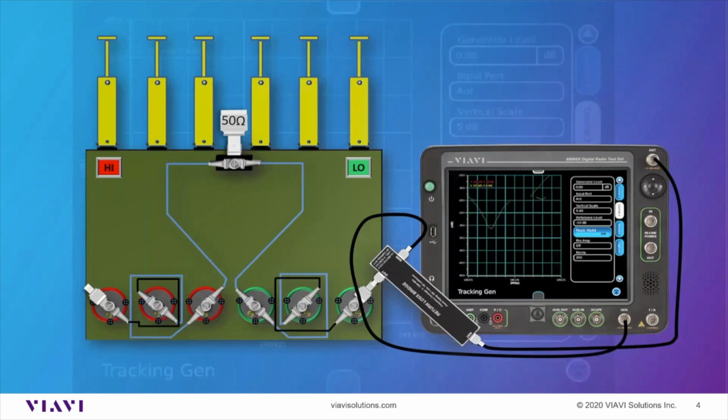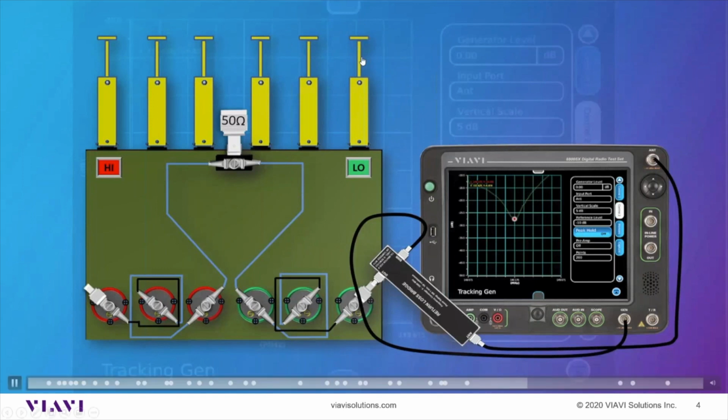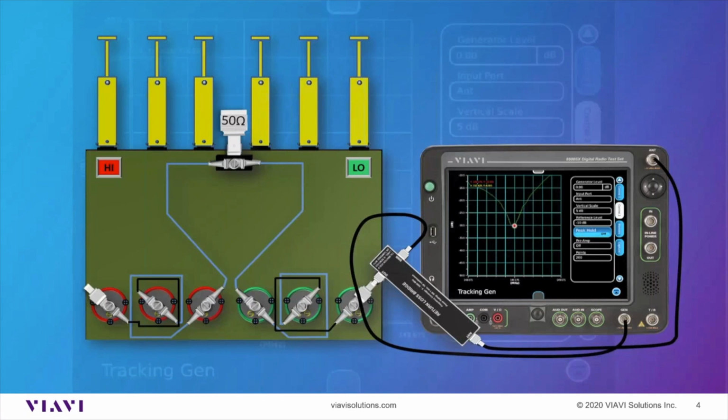So this is the art of tuning these duplexers, is this portion right here, because you've got these enormous plungers, and you just are moving them very, very minutely. So the thing is that this thing's tuned up pretty good. That's the reason that I'm only having to move it a little bit, but I am optimizing it. And you probably see a little bit of difference in the insertion loss, but I was so close that, you know, it might end up being tenths of a dB. But this is something that they would require you to do as a fine tune on these.